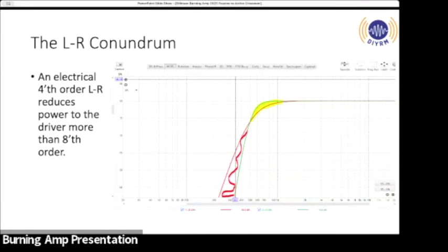So when I go to push a tweeter lower and lower in frequency, I'm actually aiming for a fourth order acoustical response and hoping that my electrical response is starting to filter off even higher up in frequency. Okay? So that's why I'm saying that this whole idea that just putting a higher filter order on it gives you more power handling, if that means that you're making that driver work lower and lower in frequency, no, it doesn't. All right?